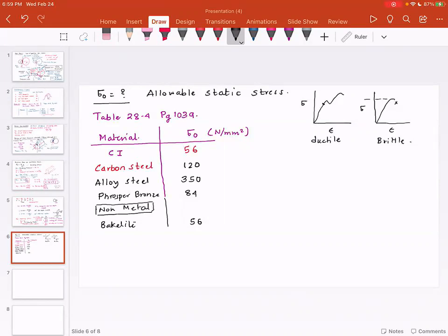Now, the next thing, and this is super important, is that the gear is always loaded under dynamic load. So even though we are looking at the beam strength design and other things, it is actually always under dynamic load. So what we want to do is come up with some sort of estimate of the dynamic load.